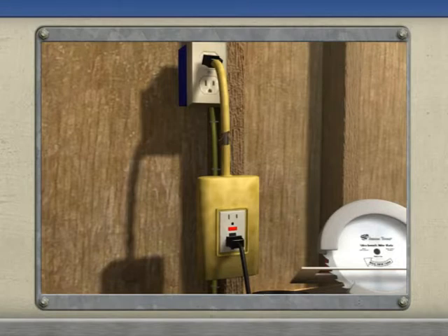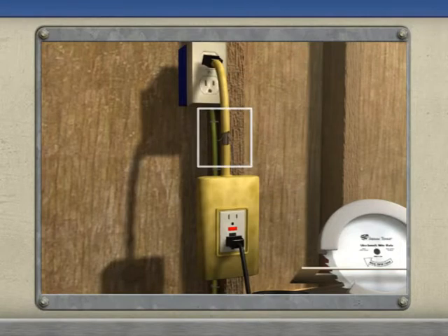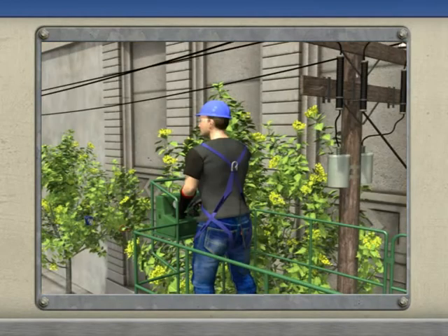The first part of a safety plan is to recognize the electrical hazards you are about to face. You must know the situations that present danger. Exposed electrical parts or bad insulation can allow current to be passed from the normal circuit path to your body or other conductive material. Power tools and wires should be inspected before handling to ensure all electrical components are properly insulated. Overhead power lines can be dangerous when operating large equipment or moving large pieces of metal.